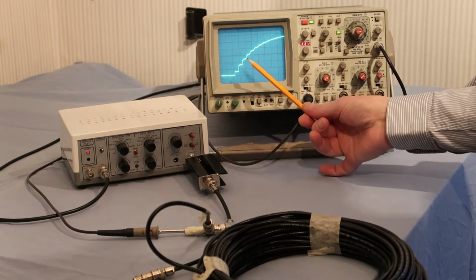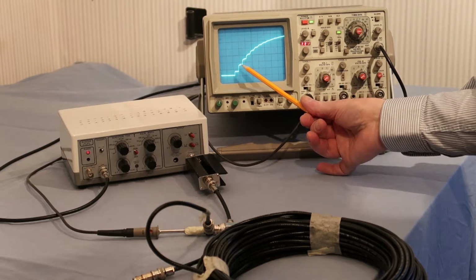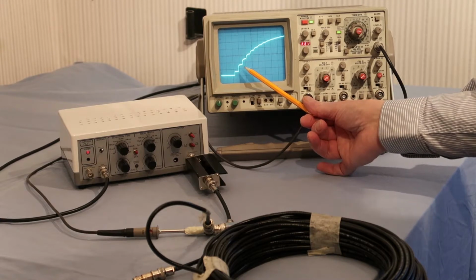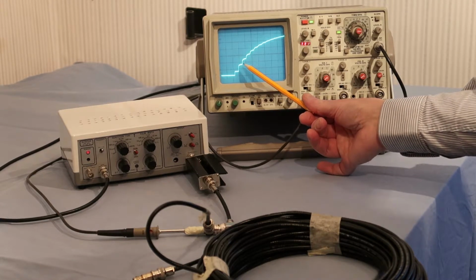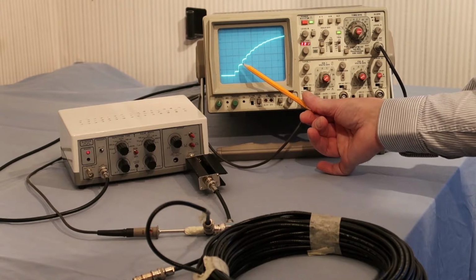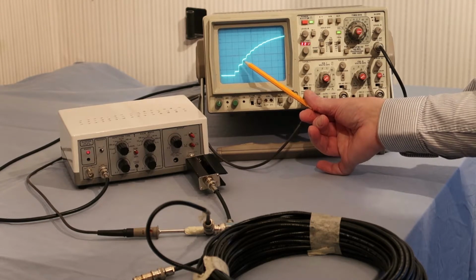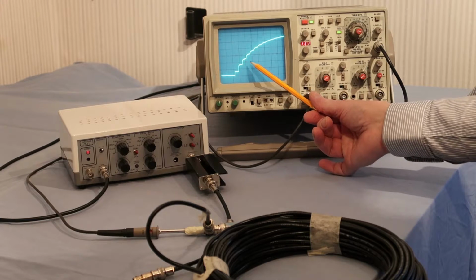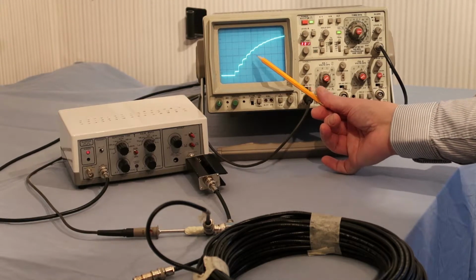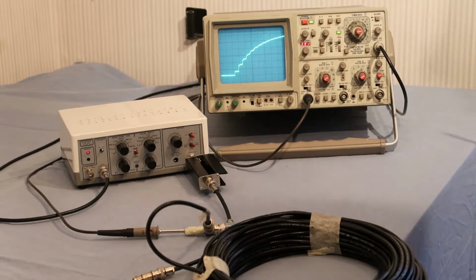First, we have voltage division. 10% of the signal is going out on the cable, 10% is coming back, and of this 10%, some of it is reflected back out, and this is coming back, and it goes back and forth like this. This is the staircase voltage we get when we charge a capacitor.